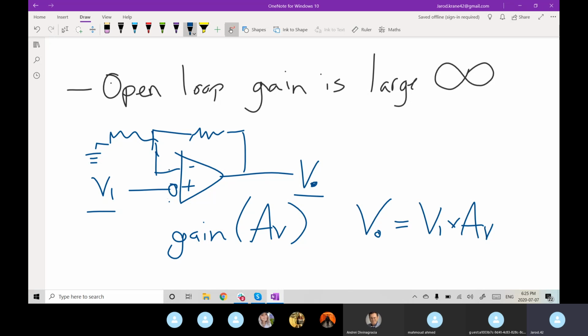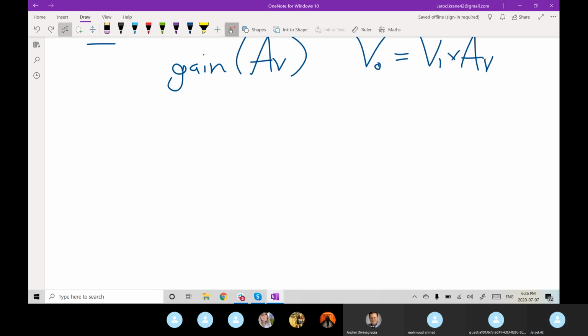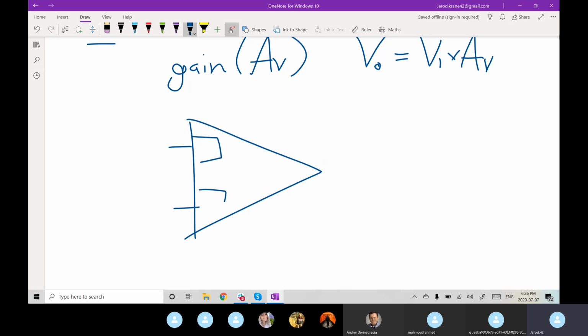And similarly, we don't have any flowing in or out of the inverting pin, although it should be tied to our output. We would assume there should be. What's happening is that the internal of the OpAmp has the inputs of both have high impedance.